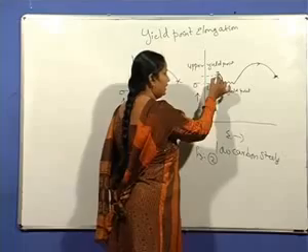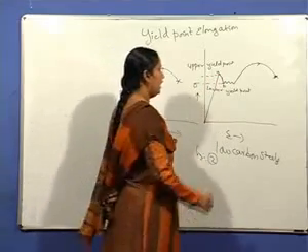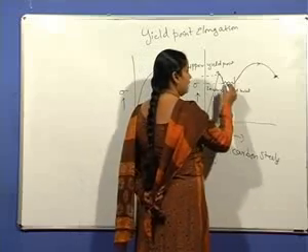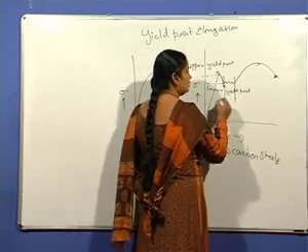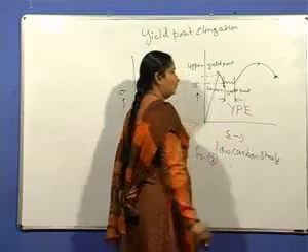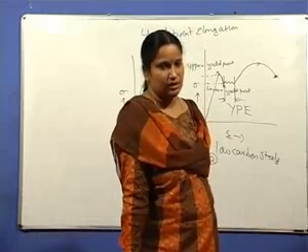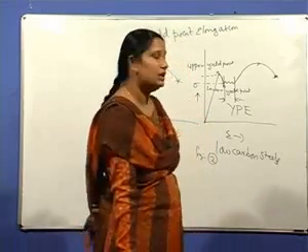So up to the point A, it is similar to figure 1, the normal stress strain curve. And beyond this, the elongation is known as yield point elongation, where the material undergoes yielding at constant stress beyond point B, that is the lower yield point.